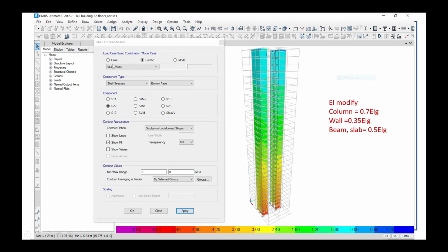Yes, we check on the surface. We check the tensile stress in the service limit state. Don't check it in the ultimate limit state, because we are concerned about stress. You have to check it in service. If you check in service and tensile stress does not